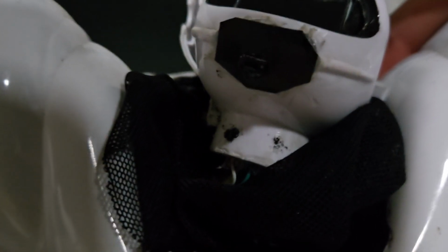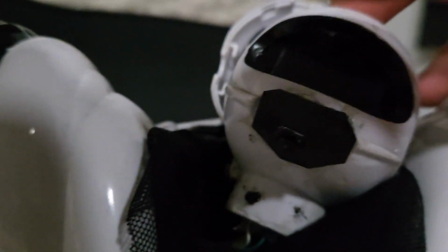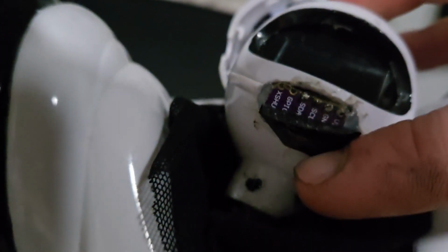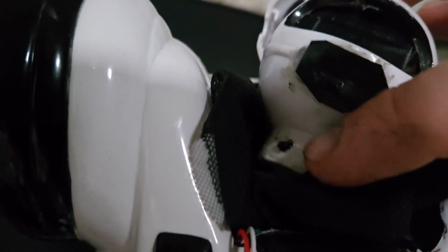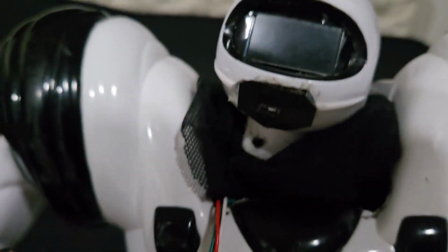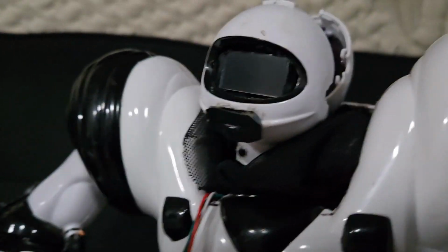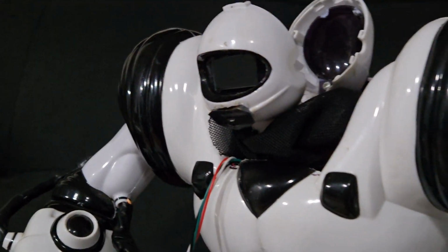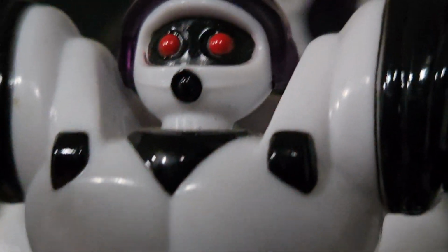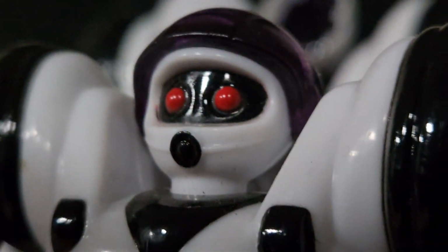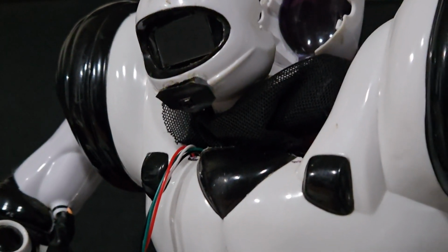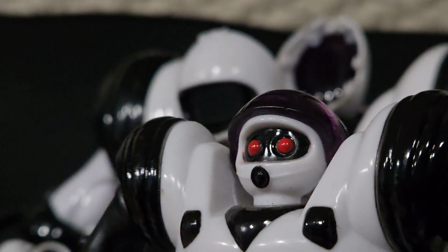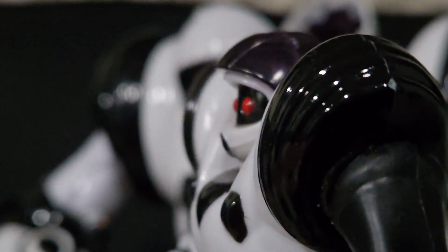Now, as for the depth sensor, that's a little more advanced. What you've got going on here is a VL53L0X distance sensor inside of the head, and it has to be trimmed down. Well, it doesn't have to be trimmed down, but the robot's going to look better if you trim it down, and then put a little piece of plastic or vinyl over it like I did. Now, if you want to use the original Robosapien mouthpiece and use a light pipe so that you don't have to have the face of the robot modified too much, just keep in mind the code will have to be adjusted so that the light pipe is reading at the correct angle.